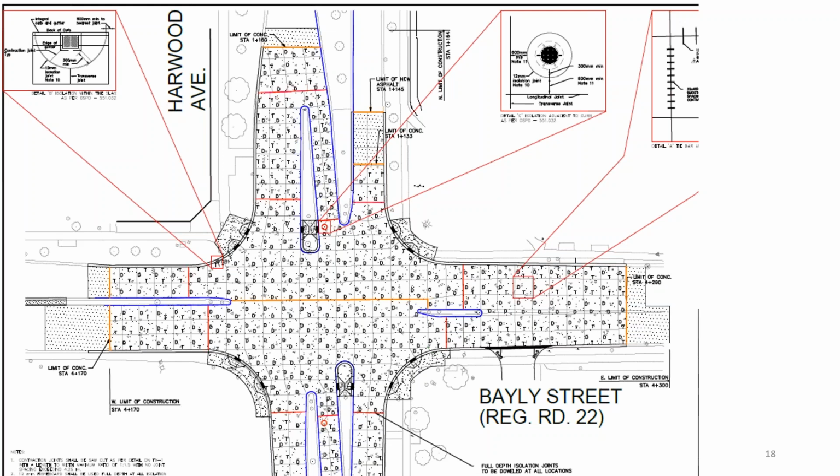There's a lot that you have to consider when you do your joint layout, because you want the panels to be relatively square, and if you don't lay it out properly, then you're going to end up with weird sort of triangles and long rectangles that are just going to be cracking. So we had guidance from that. The ACPA has some good documents about joint layout.